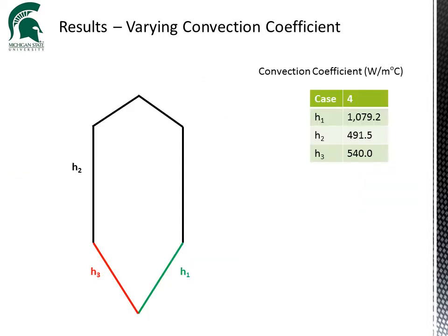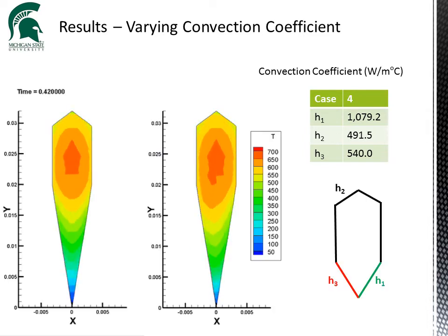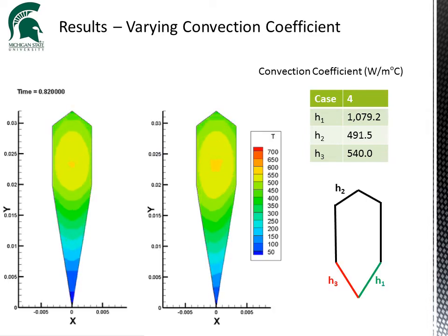Now let's suppose the swordsmith had an off day and made the convection coefficient due to the clay thickness asymmetric, which we'll designate as little h3. What you can see is a temperature distribution that is asymmetric, but it has a relatively similar cooling rate as with the proper distribution of clay on the edge.